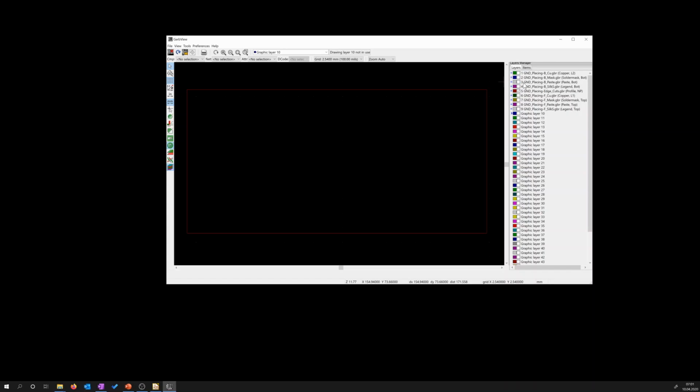Okay, the next interesting thing to check is if we have solder paste on the ground side of our board, and we see we don't have solder paste on the ground or on the bottom side. This makes sense since we have no surface mounted devices there. Okay, now we check the silk layer on the bottom side. Also, we didn't make annotations on the bottom side, so we expect we have no silk layer there. That's fine. And we are finished with the bottom side, so we go to the front side or top side.